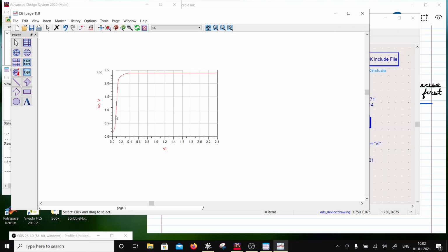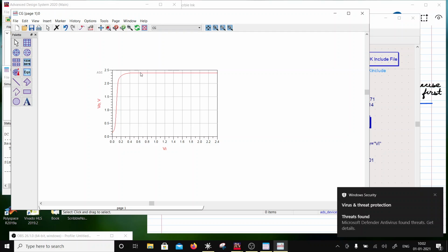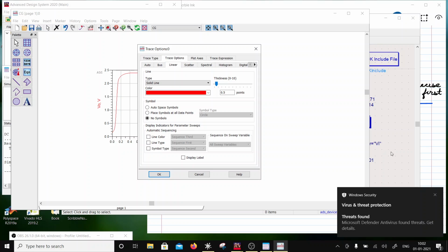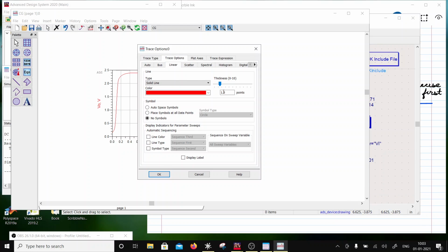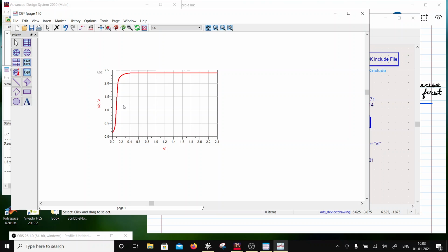Okay, yeah. So now you see that there is a complete swing. Now, if you remember, common source had a negative gain. Now this one has a positive gain, whereas common source has a 180-degree phase difference between output and input. Now here it is going to be in phase. So we are all set.